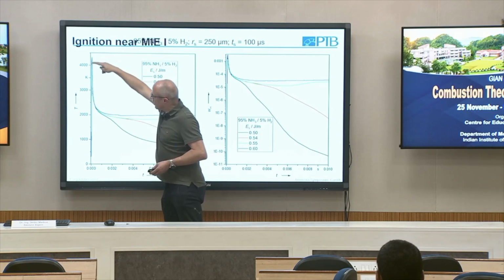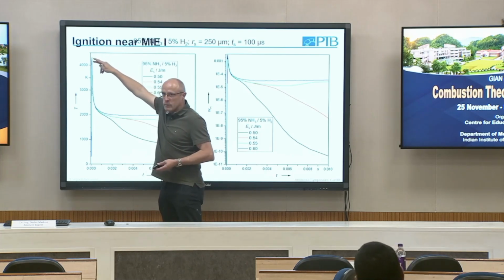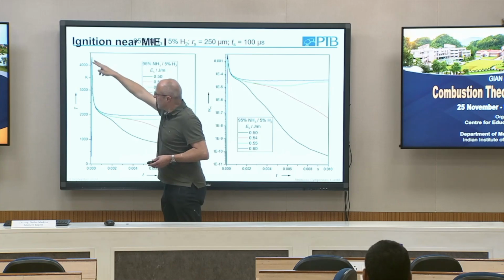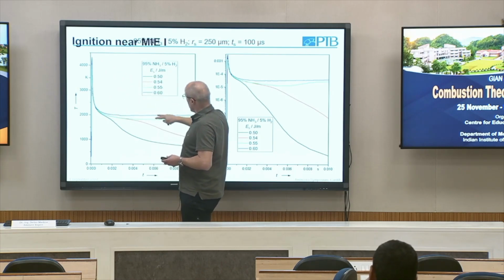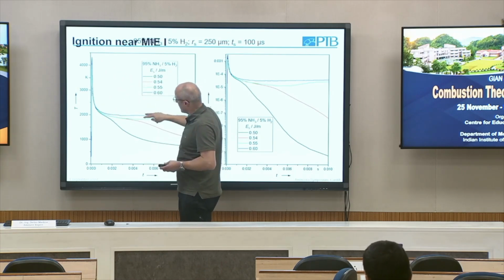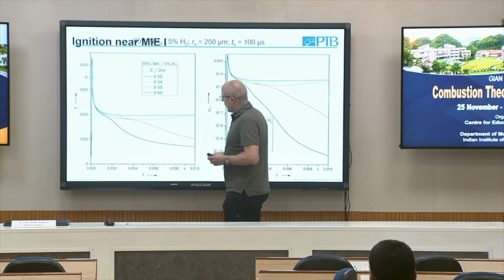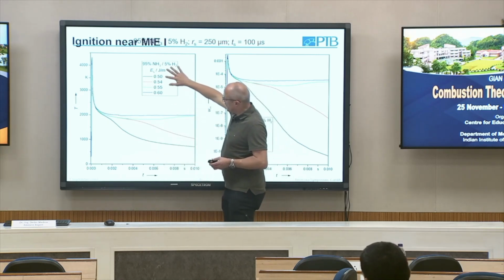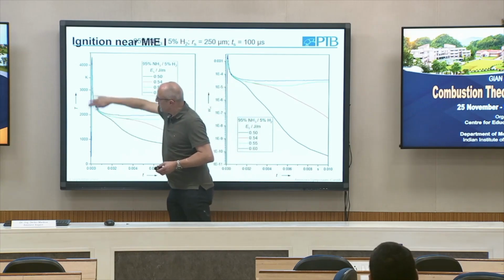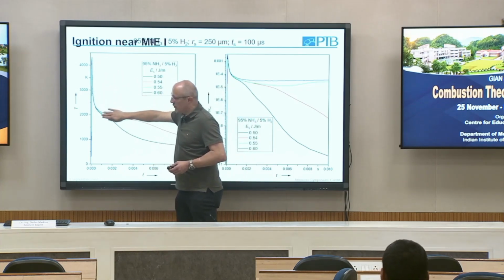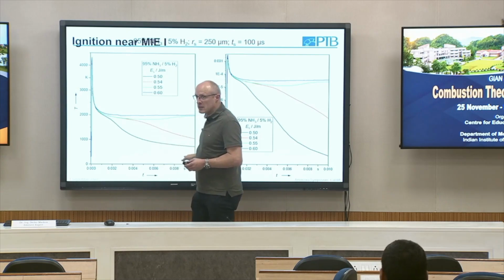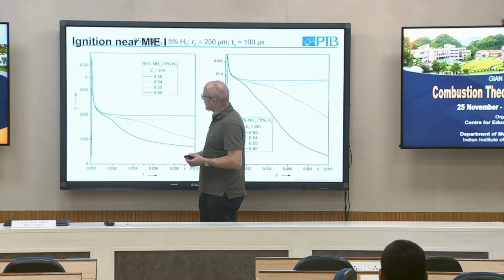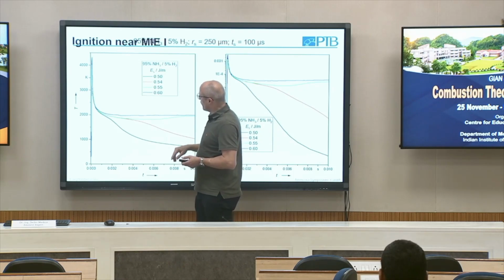So then temperature here is dominated by the energy we deposit from the spark. And then here we have the adiabatic flame temperature, more or less. If we use 0.5, we heat it up, and then no ignition takes place, the system cools down. But we also see here some interesting cases, 0.54 and 0.55 joule per meter.